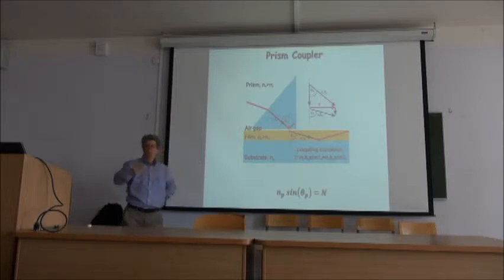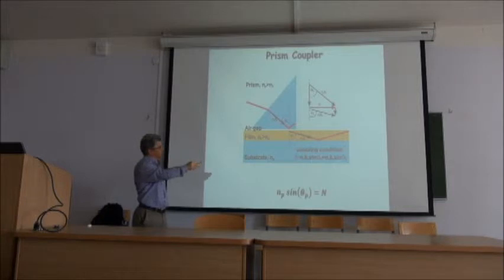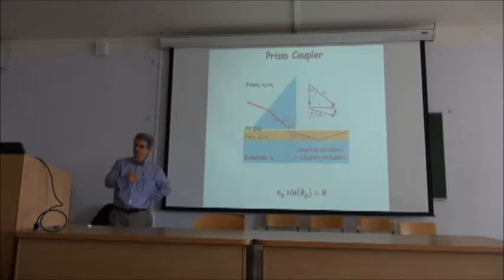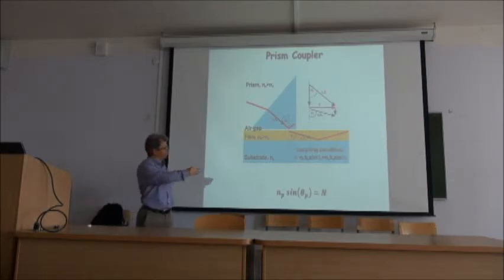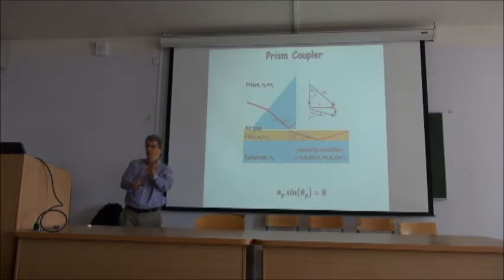So if you remove air and put water, you're going to get a faster de-excitation. It's going to start to decay faster. So then you may need to increase the gap here to minimize that de-excitation, that leakage out. If you put water, you probably want to play with the gap in order to maximize the coupling.